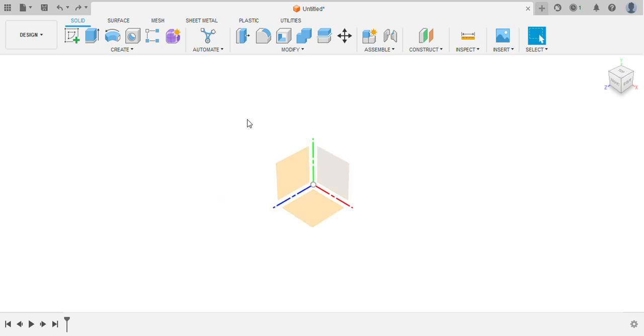So in a detailed view, if you want to check, we have an origin option here. If I turn this on, if we observe here, the black color mark is active. Black color mark active, in a sense, means the display is on. If I want to turn off the origin, just click on the eye button once again. So the origin vanishes. If I want to bring the origin back, just click on this eye option.